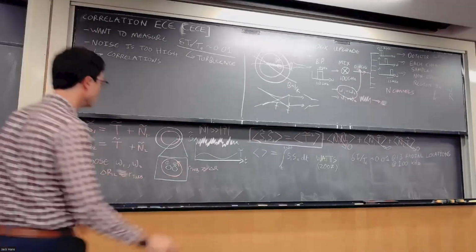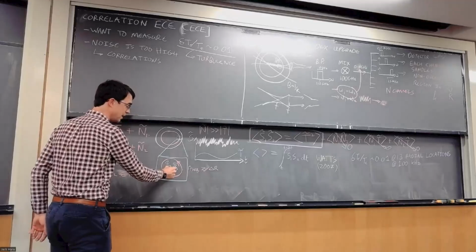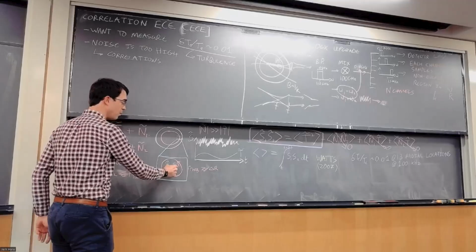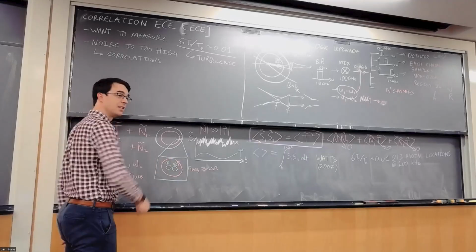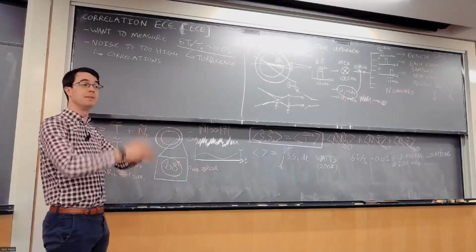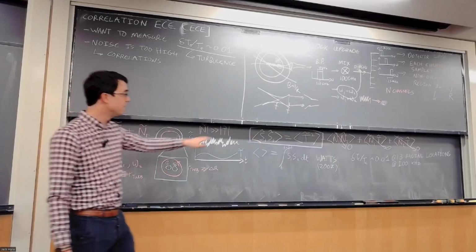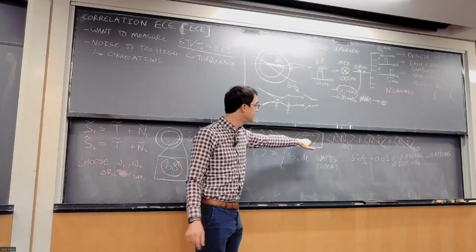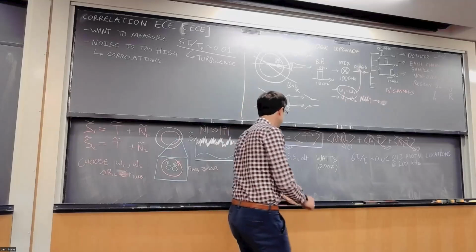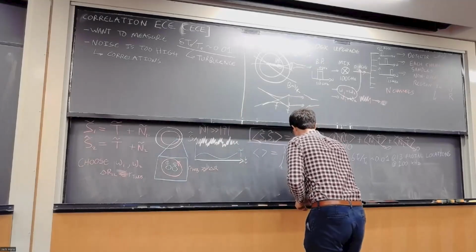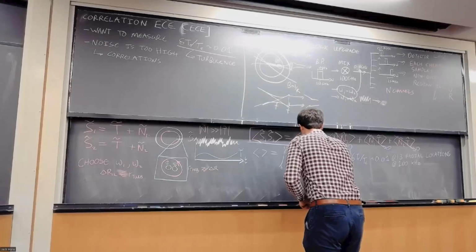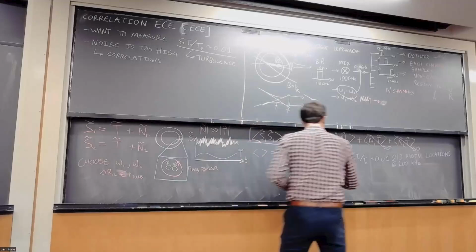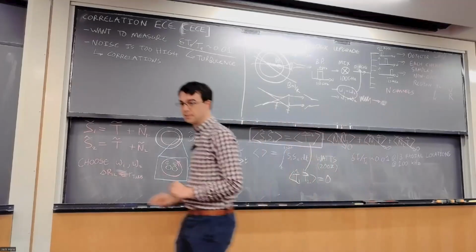Yeah, so the idea is that we have positioned these two volumes which are producing frequencies omega-1 and omega-2. We've chosen omega-1 and omega-2 so they're very close together, and we think that that distance is smaller than the size of our turbulent eddy. And within that turbulent eddy, the temperature should be the same going up and down. If you do this correlation and you get out nothing, that probably means your volumes are too far apart, because this T correlation would just go T1, T2, and there's no good reason to believe those temperature fluctuations are correlated, because they'll be part of a different turbulent eddy. And so that would just go to 0 as well.